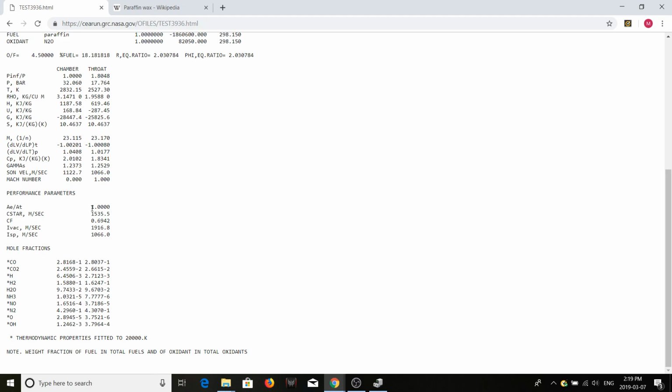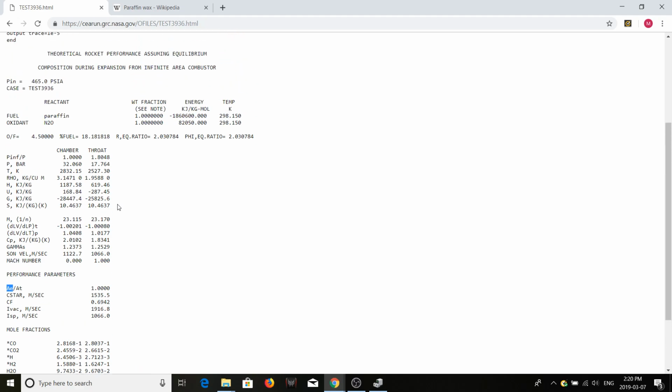Then you get at different, what is the area ratio of the column? So this is ratio to the throat. So area, it says AE, area exit, but what it means to say is the area in question. So it assumes that that area is the exit. Oh wait, I just did air quotes. I'm an idiot. Yeah, so quote unquote exit in question here. But it doesn't have to be the actual exit. It can also analyze, as I said before, subsonic area ratio, so parts of the nozzle prior to the throat. So yeah. Anyway, this is how you use it.